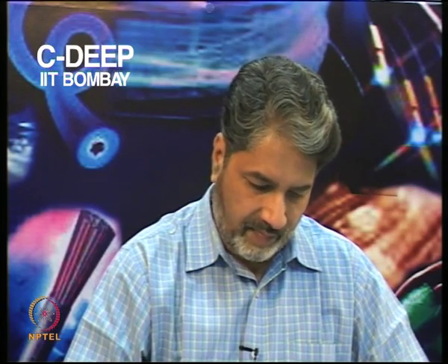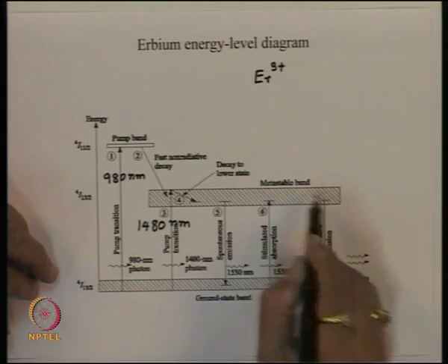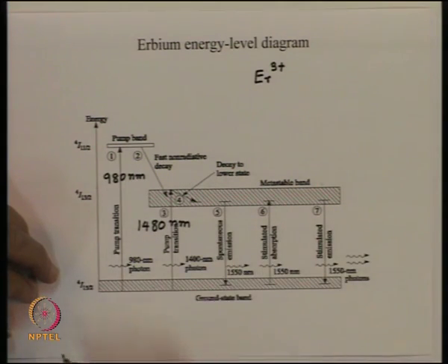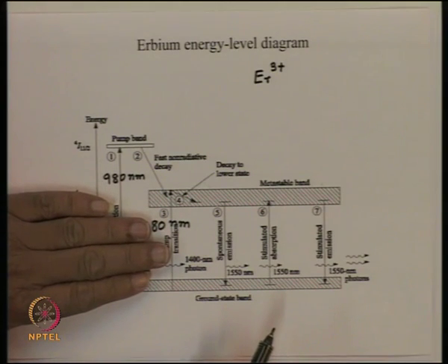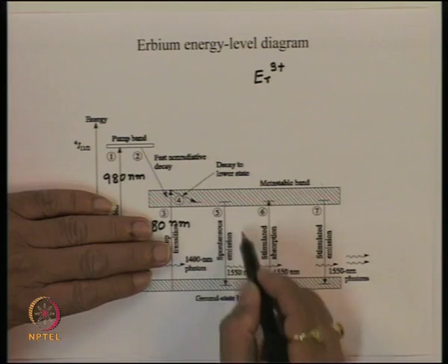We also see now that if we do not put any signal inside the amplifier, then because of the band diagram we create population inversion, and now you have the electrons accumulated in this region which will make a downward transition. Since there is no signal present here, the downward transition will be because of spontaneous emission.